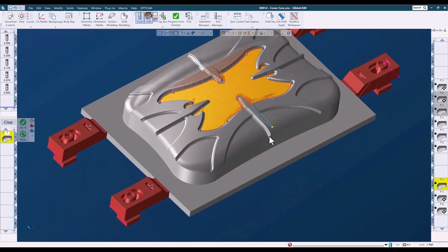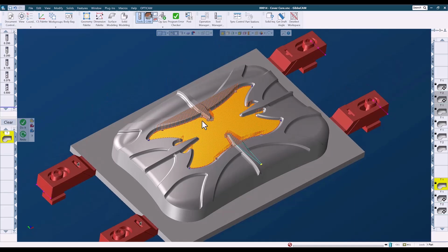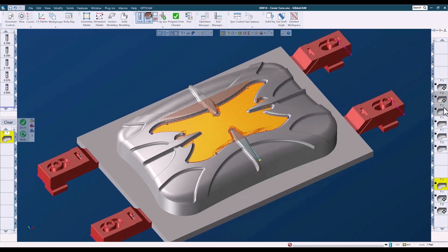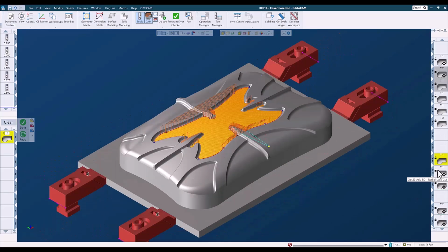retract frequently to jump over areas that aren't part of the cut, but that are in line with the linear strokes of the toolpath. So while a linear lace cut is entirely appropriate for this toolpath, it's not one that we would choose for this toolpath. Let's look at a few toolpath choices that might do a better job for us on this.